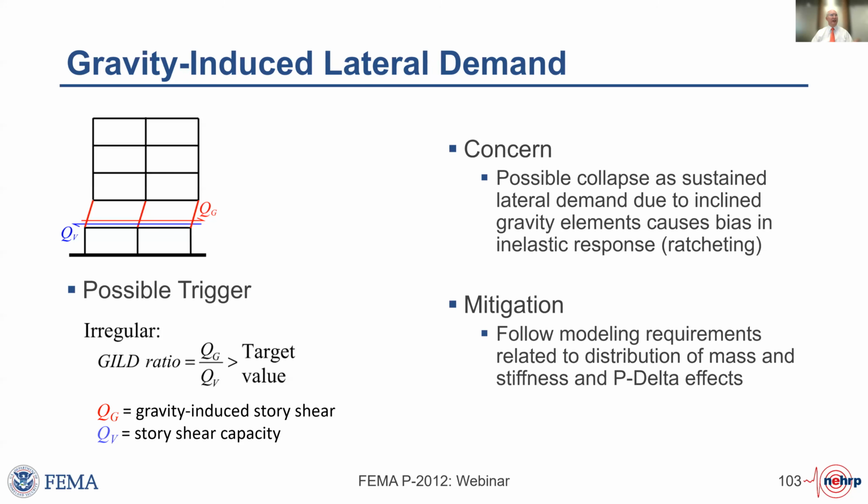In the case of this simple cartoon, all of the weight above the red columns is at one location in plan, and that same force has to be at a different location in plan below. And so there's a horizontal shear that resolves into the system. And that shear has to be resolved in the lateral system because that's the source of lateral strength and stiffness.